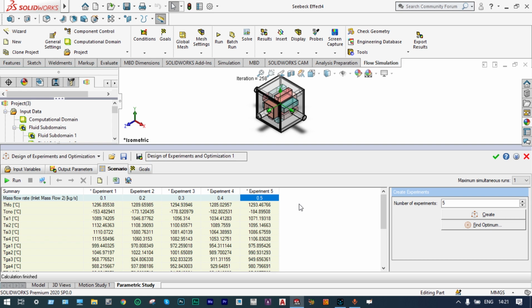Instead of stopping here, we can go for further studies. That means with the temperature difference, we can connect this with voltage, and finally from the voltage we can generate electricity or current. For that we need some mathematical calculations. We know that temperature difference is directly proportional to the voltage, and voltage equals alpha into temperature difference, where alpha is a constant known as the Seebeck constant. That alpha is dependent on material properties. With further studies, we can find this relation between temperature difference and voltage, and from this voltage finally we can generate current or electricity.